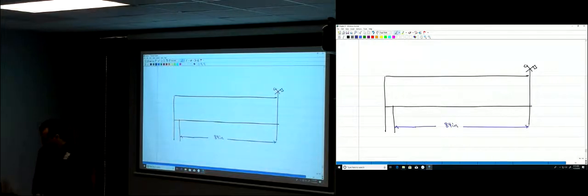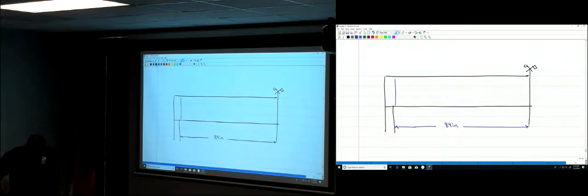I want to provide my stirrups. I'm going to provide my first stirrup at 2 inches from the face of the column. So that's 2 inches here. And then the spacing is 4 inches, right? So one stirrup here, and then this one.